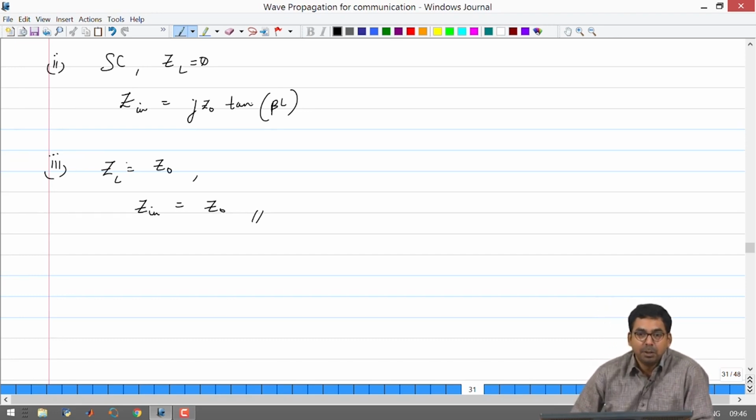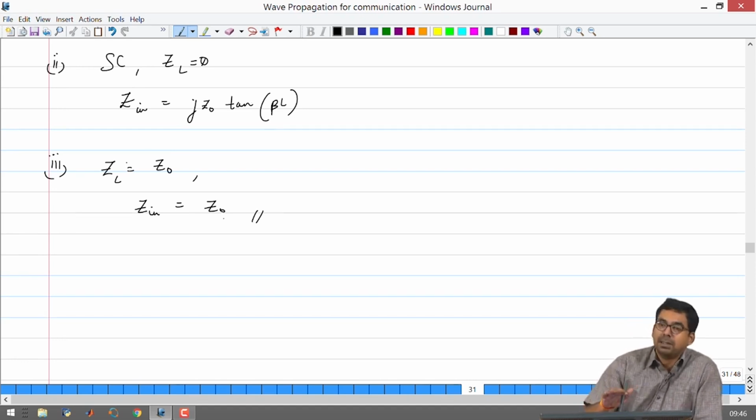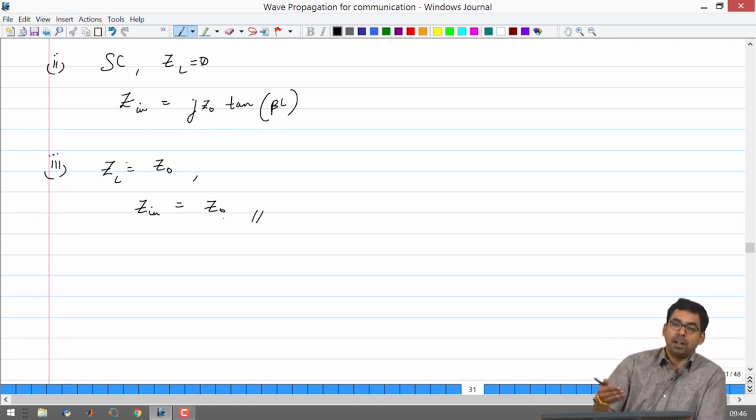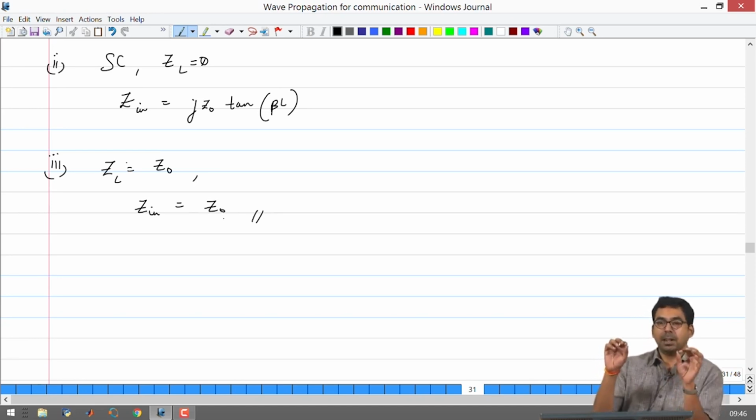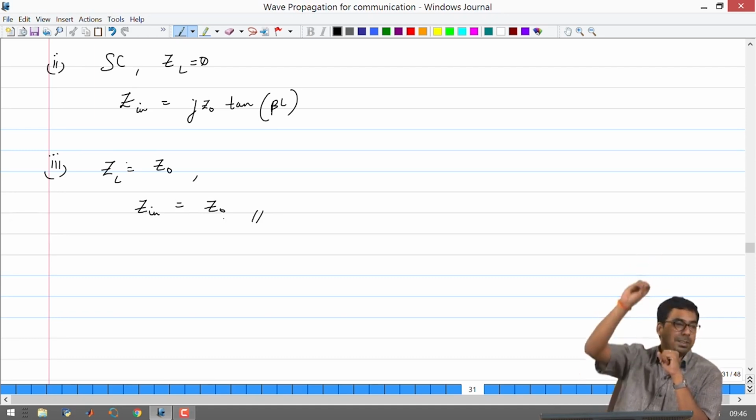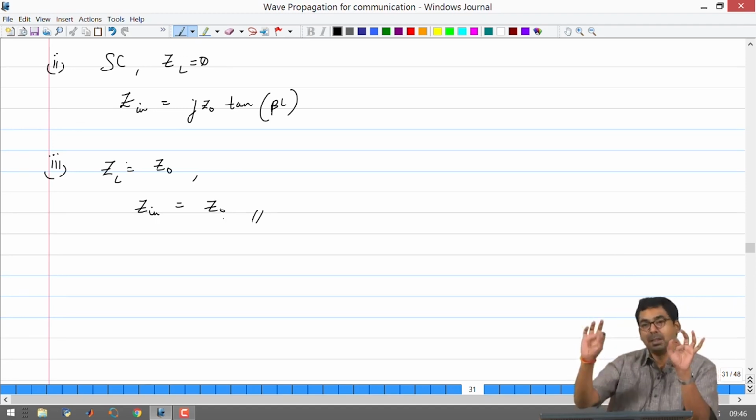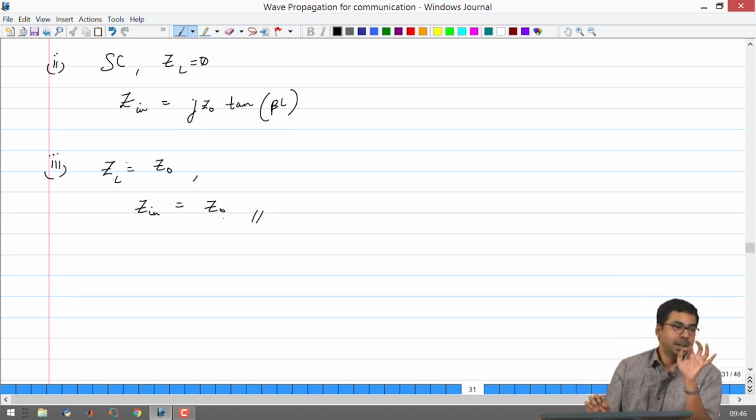The program that we have written, you can always substitute a cosine or a sine and try to see what happens. Here, mind you, we have considered only the spatial distribution. We have still said that with respect to time, it is going to be time harmonic or periodic. So, it means that even though you will have some places in your transmission line having non-zero voltage, with respect to time it will go to a maximum and then go to 0, but the nodes where it is 0 are going to be fixed all the time. So, some small things will appear only if you take that simulation that we had already done and plug in a cosine or a sine just to understand what that means.